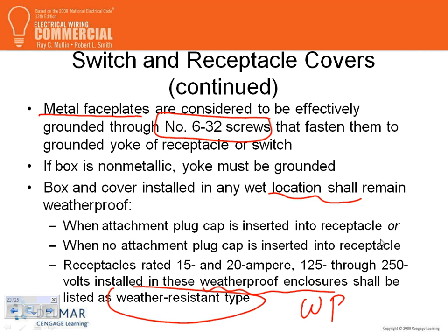What did you say about the bubble? The bubble in non-residential, can you put that one? Non-residential, the bubble, you cannot, because it has to have a heavy duty cover, and that plastic bubble does not qualify as heavy duty. So you're talking about metal. Yeah, it will be a metal one that sits like this with a cover, so when you put your conductor, it's covering it. I have a picture, I'll show you if you research it. It's a heavy duty metal box. I think they just get sick of that cover sitting there, somebody kicks it with their foot and breaks it.